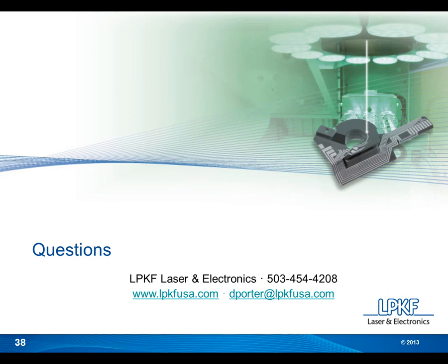Jim wanted to know, what are the circuitry limitations for LDS compared to a PCB or flex? He wants to know if a circuit on a PCB can be replicated on an MID created with LDS. It technically could be. So for an MID, and we talked about design limitations here earlier, what we see as middle of the road design guidelines for MIDs is typically 6 mil traces and spaces, or 150 micron traces and spaces.